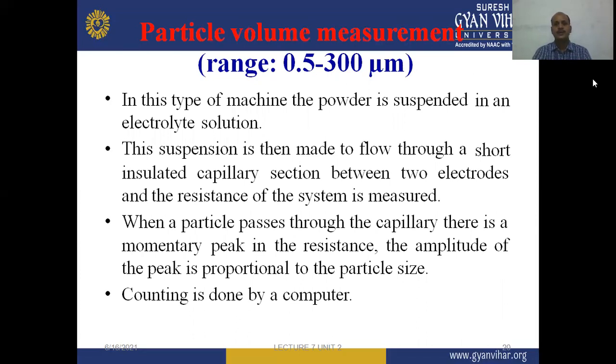Now, after the sedimentation method, which was totally based on Stokes' law, we have to discuss the particle volume measurement method. So this is the fourth method for particle size distribution. We can measure the particle size in the range of 0.5 to 300 micrometers. So we can say that very fine particle sizes can be determined with the help of the particle volume measurement method. This method has different names like the conductivity method or Coulter counter method, because the Coulter counter apparatus is